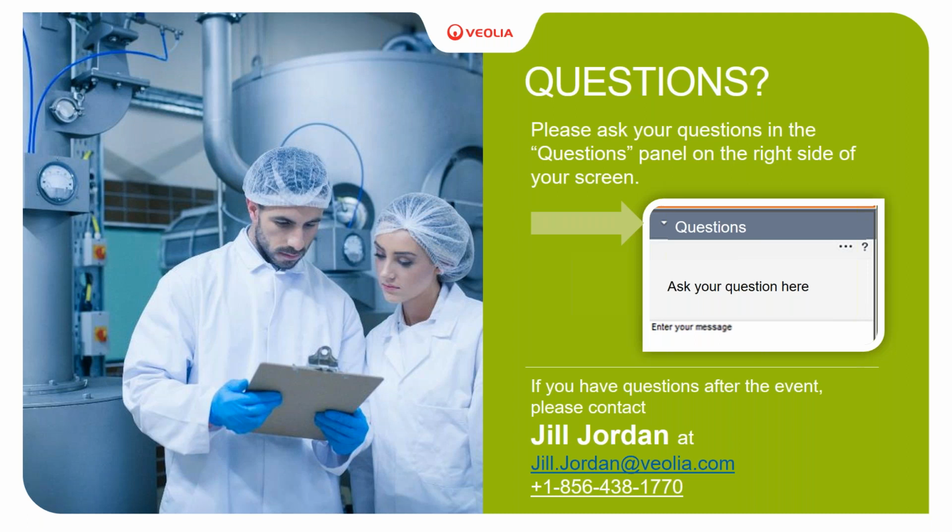So theoretically you can start a UASB or EGSB reactor with flock biomass, but you have to keep reseeding, which gets to be expensive because you need a lot of trucks, and the transportation cost is really, really high. So for me, it's always better to seed with the granular sludge into high rate systems and even in lower rate systems, because the transportation cost is lower. If I haven't answered your question, and that person is still on the line, send me an email and I'll try and answer it better.